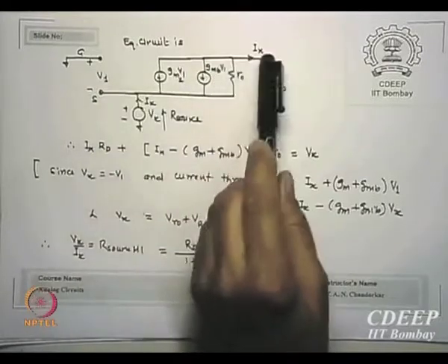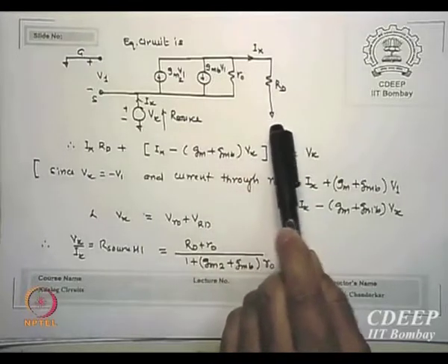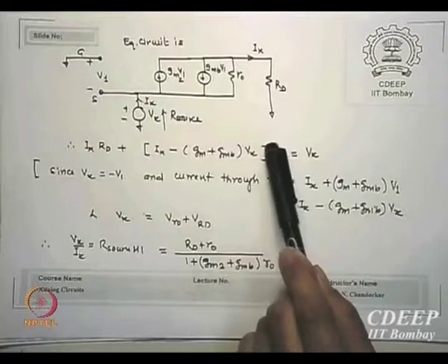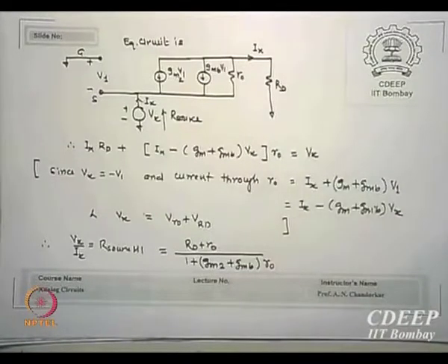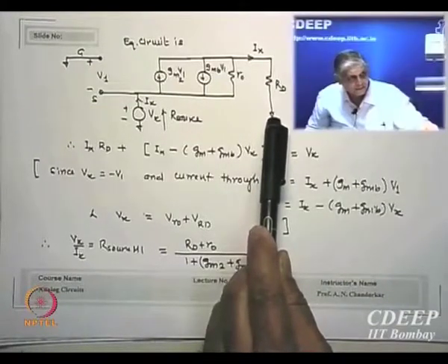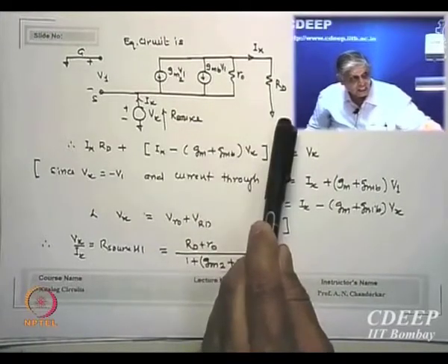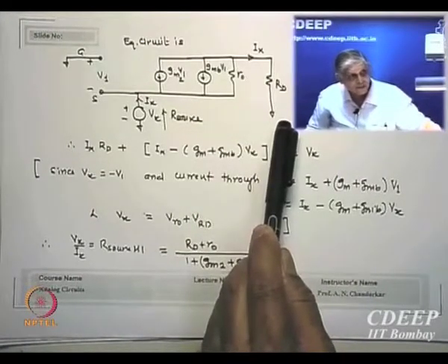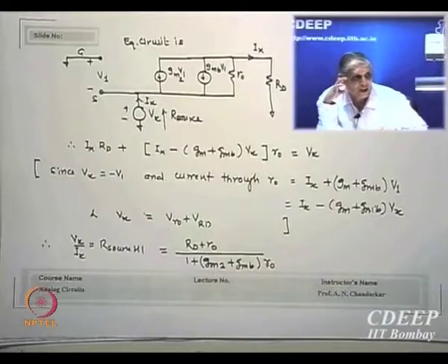R0. And finally, from the drain of that, is that clear? The resistance RD is not connected to the source but to the ground. RD is AC ground at the VDD. Please remember RD is not connected here; it is connected from the upper side to the ground. R0 is between drain and source, but RD is not between drain and source because the source is not grounded.